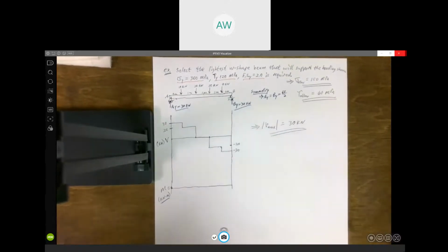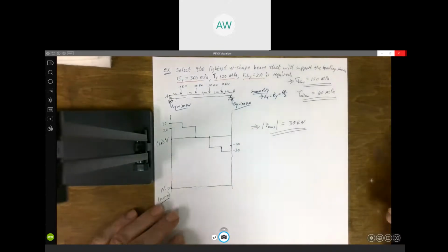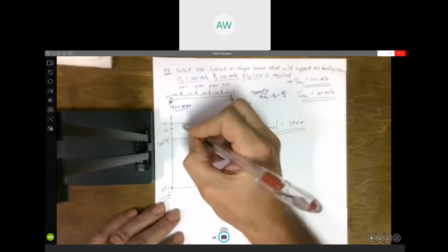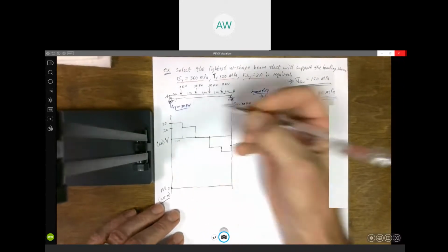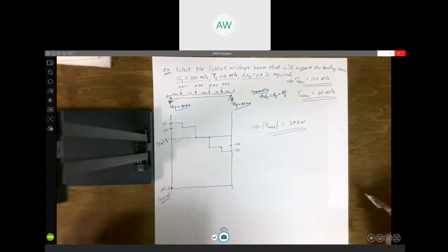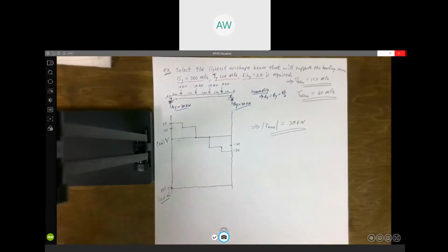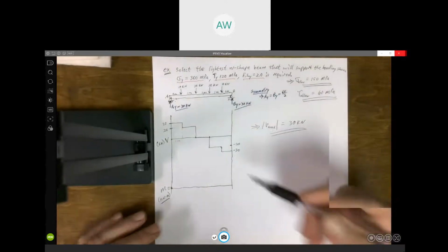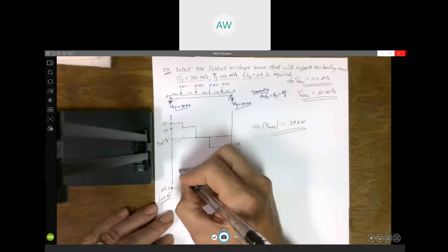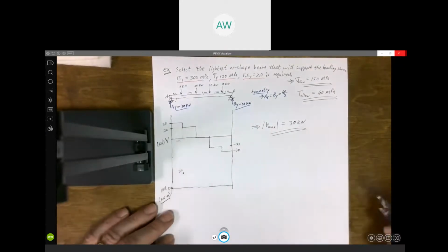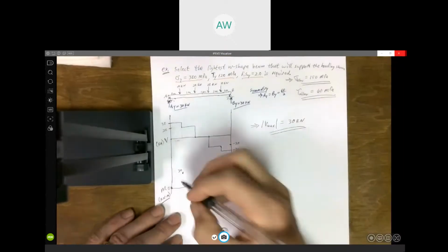And we're going to go up or down, whatever the area is under the shear curve. So here, this is again 1 meter. That area is 30 times 1, which is 30. And it's positive, it's above the axis. We're going to go up 30. So we're going from 0 to 30. Again, the shape of the curve, it's 1 degree higher. This is constant, this is linear.